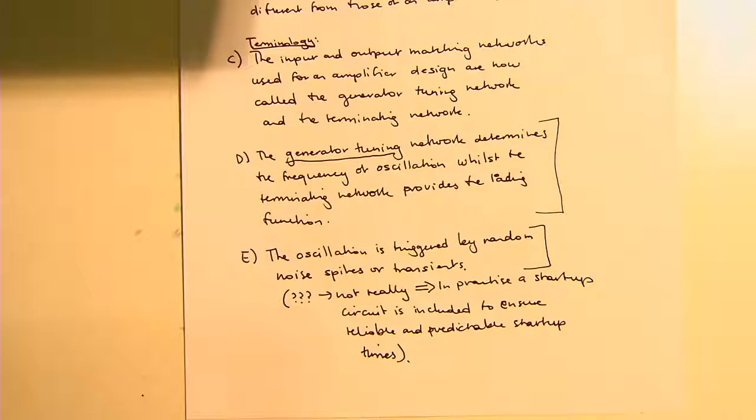But generally what you do in these networks is you also build a startup circuit, which gives the system a kick once you power up. So it starts oscillating within microseconds after you hit the power-on switch. That's a little bit of engineering know-how, of real-world work you've got to do when building a real system, compared to when you read a textbook, where the person who wrote it has probably never designed an oscillator in their life.